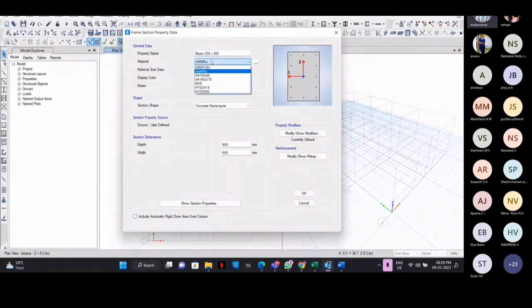In some cases, a beam can go up to 600 or 700 as per our needs. And even a width of 300 or 400 can be used. We can design as per our needs. We go for M25. Now we have chosen the material of concrete we are going to use for the beam. Now we need to choose the type of steel which we are going to use in these beams. And before that, we need to set the dimensions of the beams: depth 300, width 200.